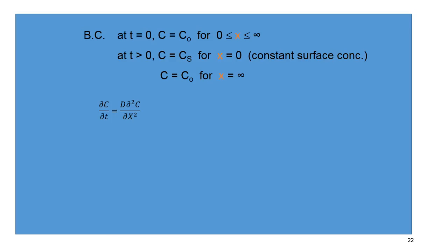Okay, if we write down the boundary conditions as we talked about in this format, and then use them to solve this differential equation, we end up with this relation between the concentration value at point x and time t, and the other known values. In this relation, C0 is the pre-existing concentration, Cs is the surface concentration, and this is an error function of this value. x is the position, D is the diffusion coefficient, and t is time.